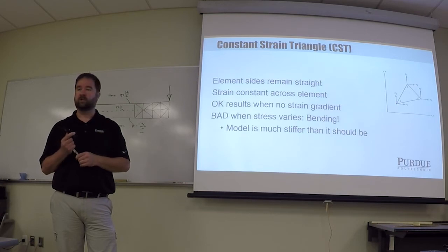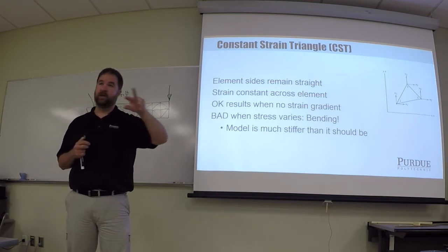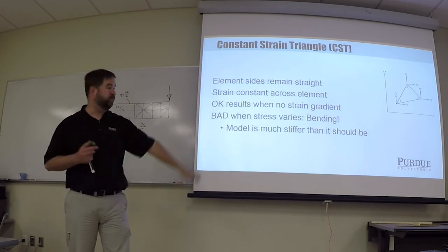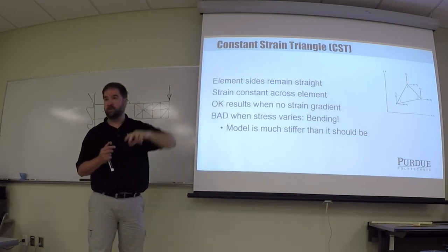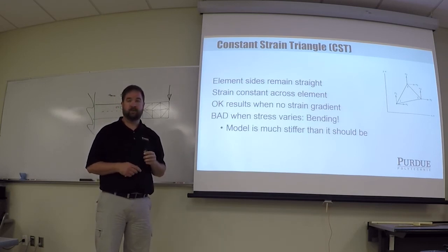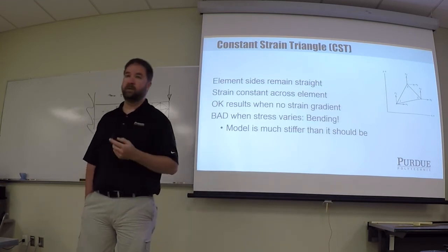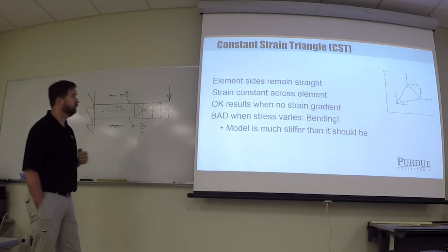The coarse mesh or the rough analysis, I forget the terminology, we'll have to look at SolidWorks. But there's two choices. You can either do, I think maybe, a rough analysis and then a fine analysis. The rough analysis uses CSTs. The fine analysis uses LSTs, which are linear strain triangles. But the LST requires more time, more computing resources, more file storage, and so forth.